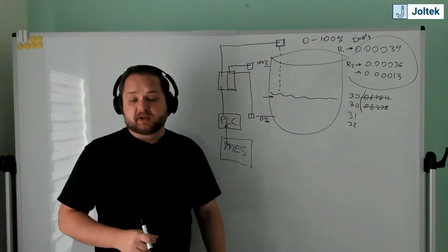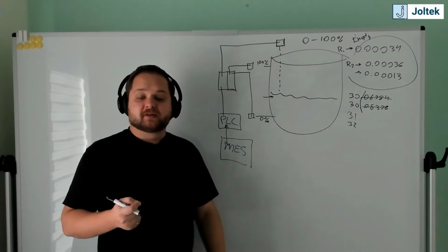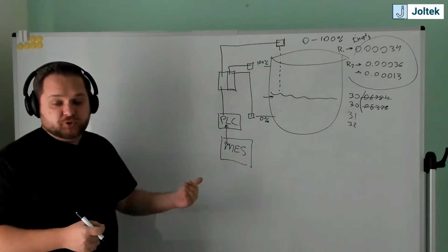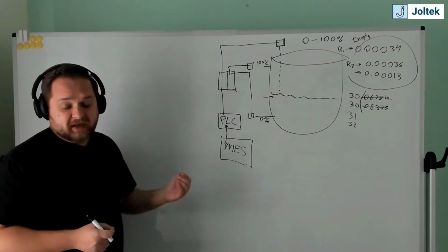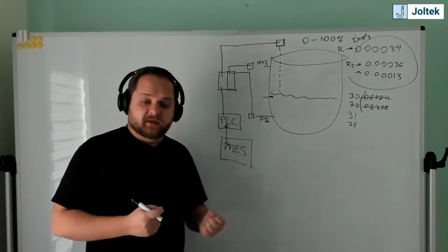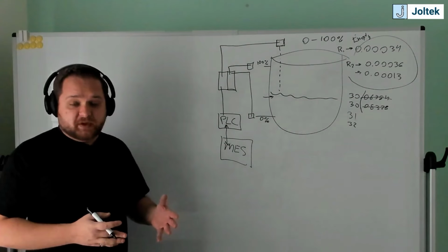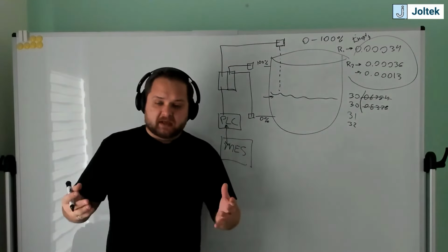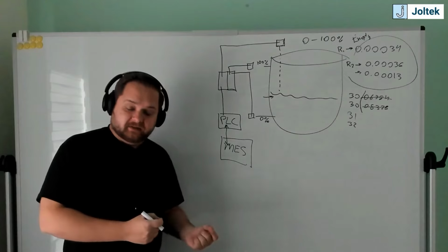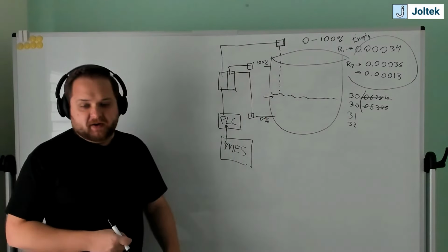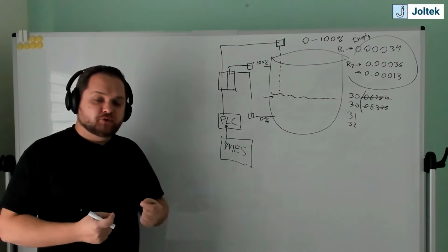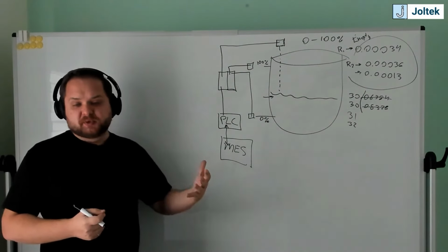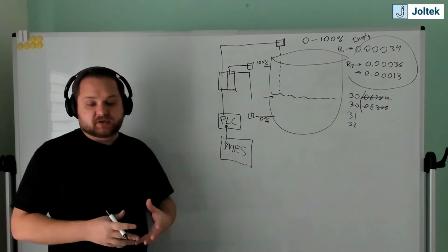Now, the problem that you can maybe predict is that this is a tank distance sensor application, but in other scenarios when you have the same analog sensor, that is going to actually matter. You're going to need that decimal point up to a certain degree to send to your MES system. And so what happens in manufacturing and in industrial data is that it is not that easy to draw this line. Where the line is going to ultimately fall is between sending too much data, thus getting charged for storing and processing that data, depending on who the vendors are, or sending too little data, right? For example, if I only capture this data every 10 minutes and my tank fills in 5 minutes, then you're going to lose resolution, and thus you will not be able to understand the process in front of you, and you're not going to be able to make decisions that make an impact on the process and solve any of your problems.